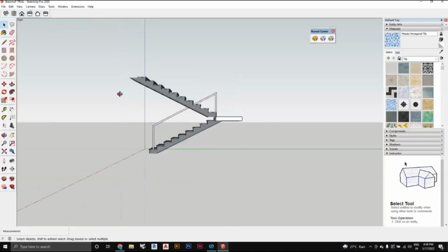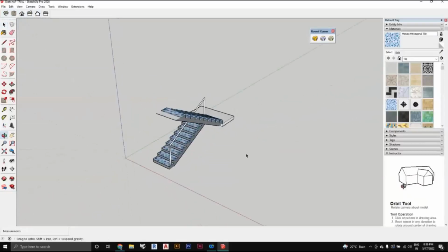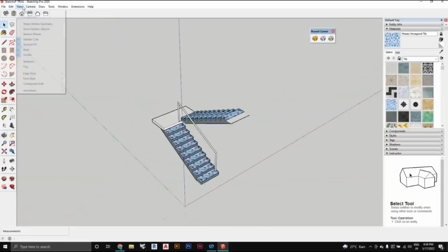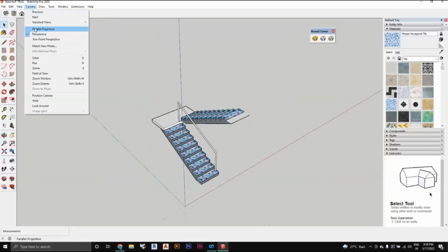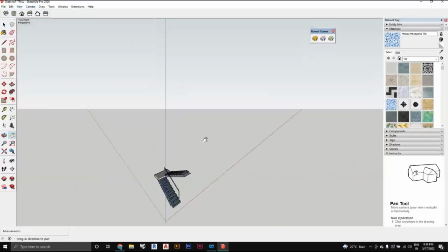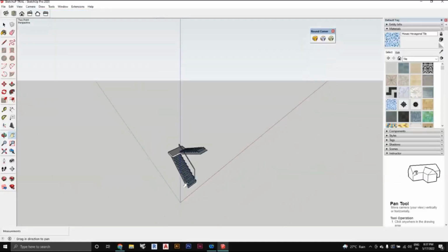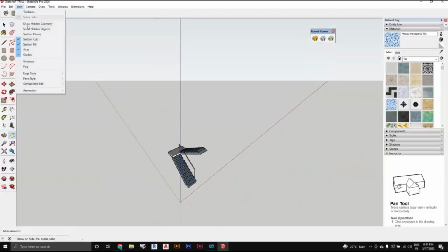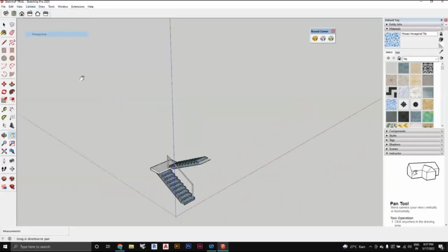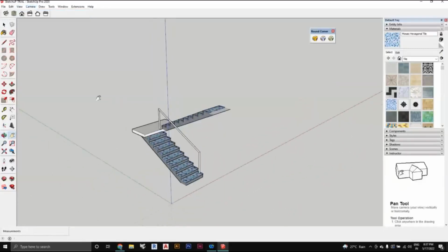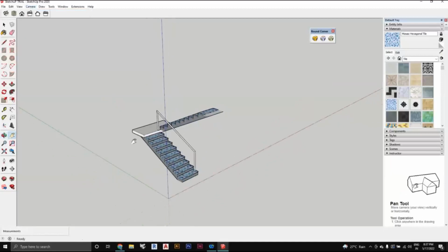But normally while working, we work with perspective views, and while exporting, we normally use the views in camera in parallel projection. You can also use the 2-point perspective, which is rarely used, because in that case you will have two vanishing points. Got it? So that is rarely used by us. Fine. You can make it perspective while working, and while exporting you can use the parallel projection.